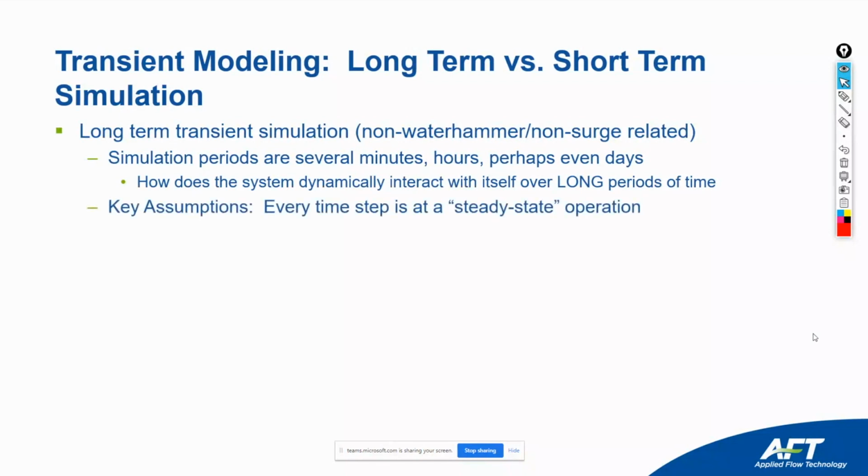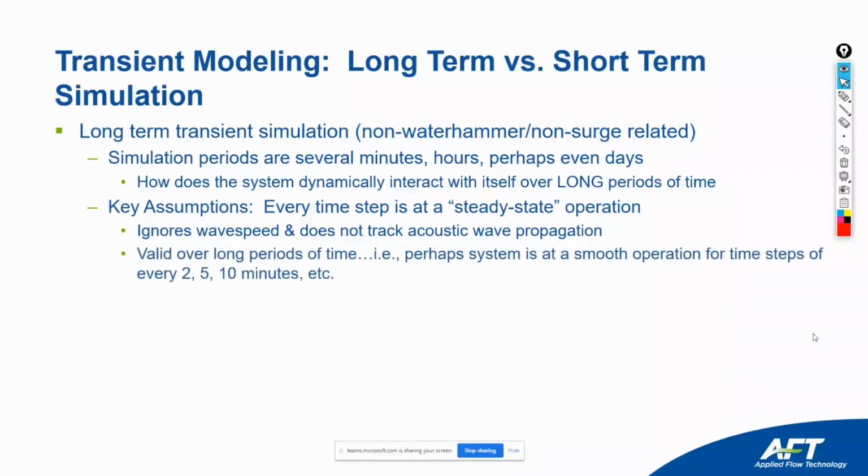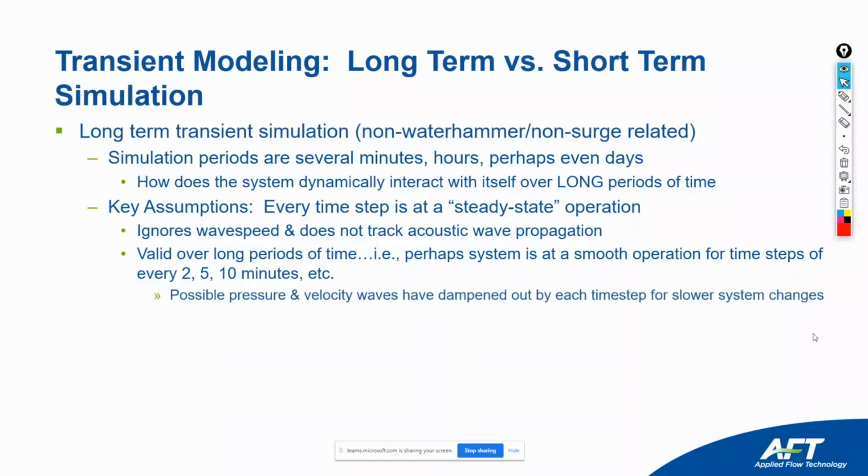Some really important assumptions: essentially every step is at a steady state operation. It's ignoring the wave speed and not tracking the pressure and velocity wave propagation in this type of transient analysis. So this is valid when you're running your simulation for long periods of time. If you have a simulation of 10 minutes and your time step is every minute or so, then that could be a valid assumption. And it might be where all the pressure waves have dampened out between time steps in that case.